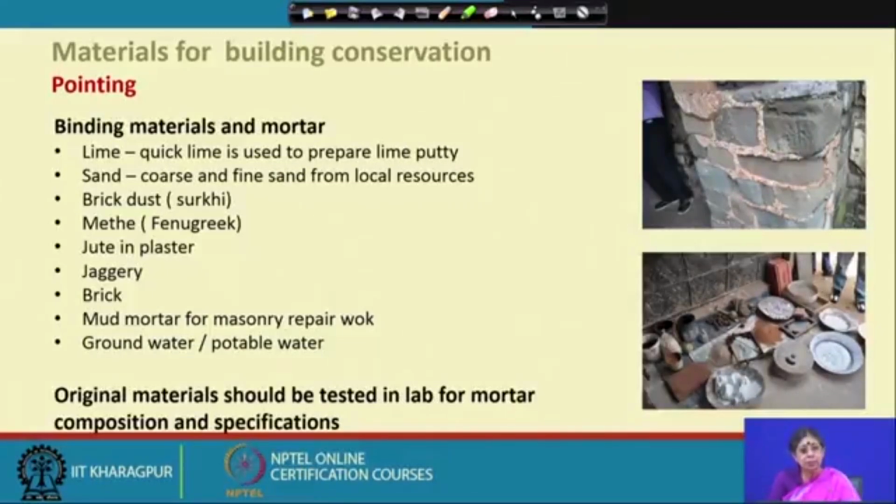Adhesive definitely can be mixed, but one has to be very cautious: what is the adhesive, in what proportion, what is its impact on the major masonry work, and the skill of how it has to be done, and the cleaning, the processing. There is a step by step procedure which has to be properly taken care of. So, as I say, pointing in old masonry structure is a very important part in terms of skill and the material.